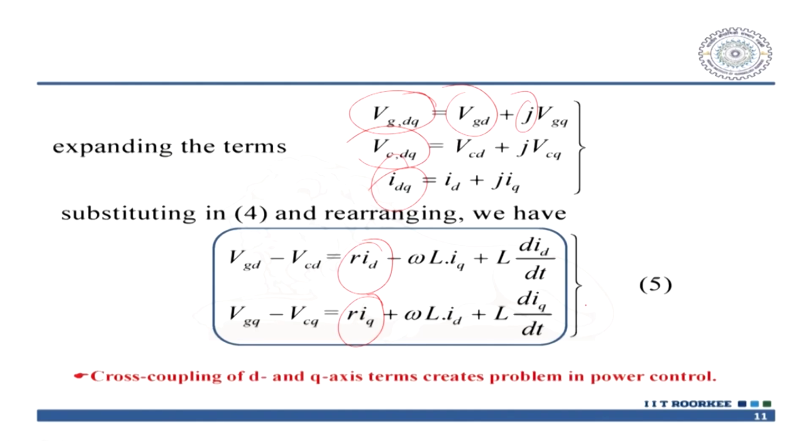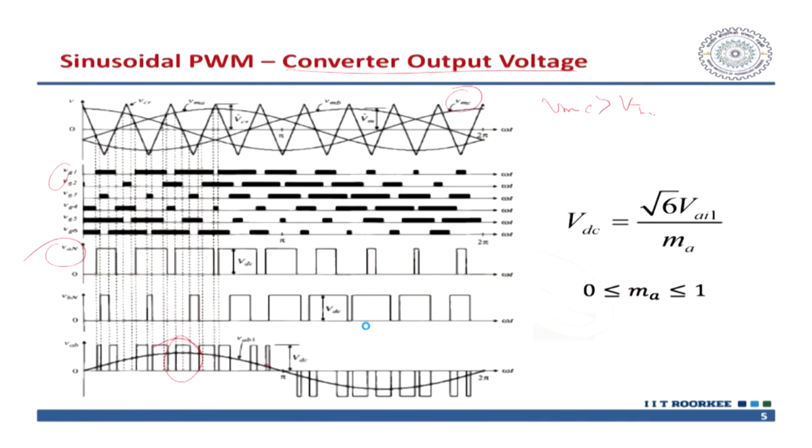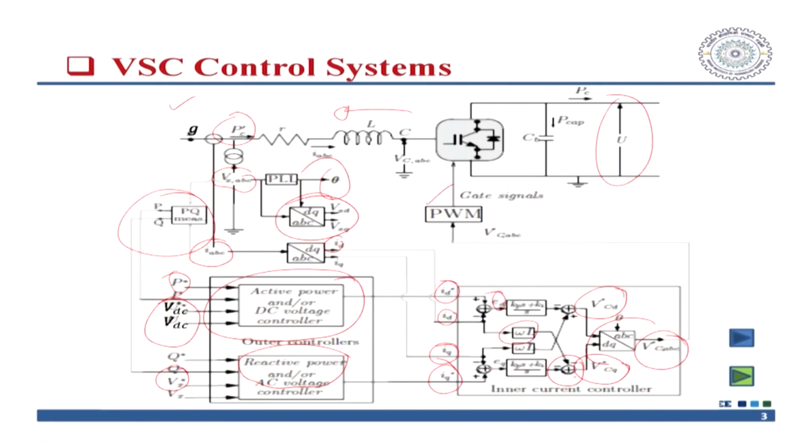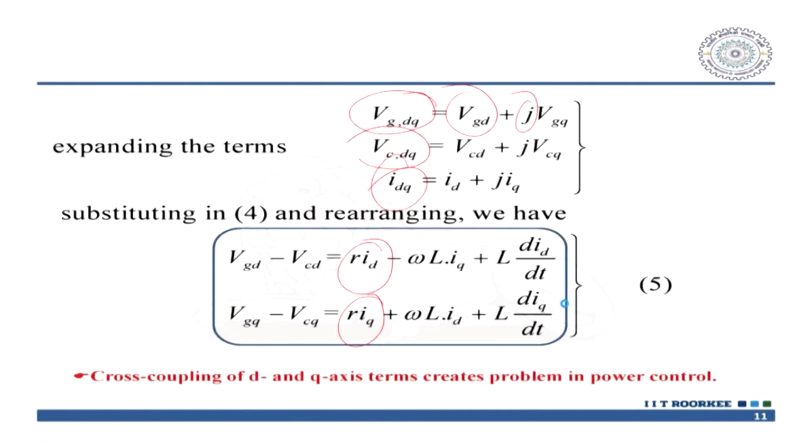You see that these are coupled equations, because, please go back, I have shown this in the control algorithm. There is a cross term, you have multiplied with omega and added up. So, this is your omega L and this is the cross term being added. Similarly, this is your cross term being added. For this reason, this is the q axis equation, but there will be a term of Id, and this is a d axis equation, ultimately you will have a cross term with a minus sign.